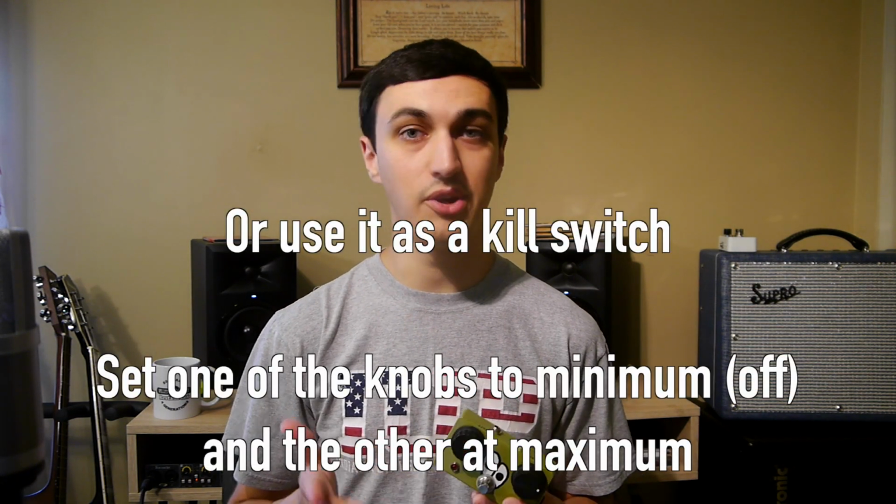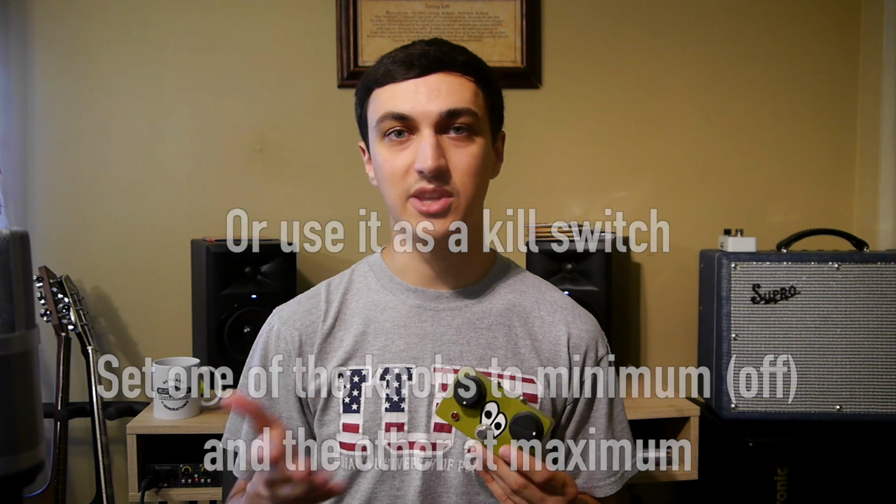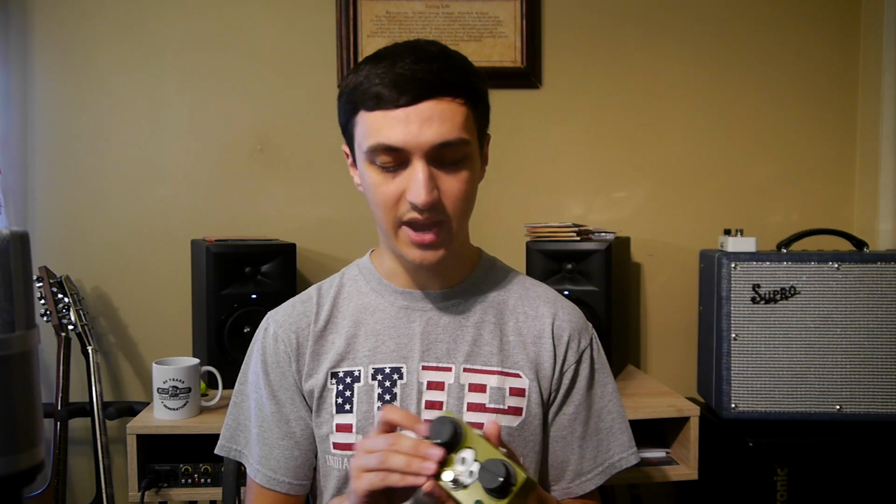So on this green side, when you hit that side, it's going to be sending a little bit less signal than it would get. And when you switch to your guitar with single coils, you're sending your full max sound. So put this at the beginning of your chain, and then after this, whichever guitar you switch between and the channels, you can make sure that your rig's getting the same volume, so your front of house engineer, or if you don't have one, you don't have to worry about what the audience is hearing at different levels and how you're sitting in the mix.